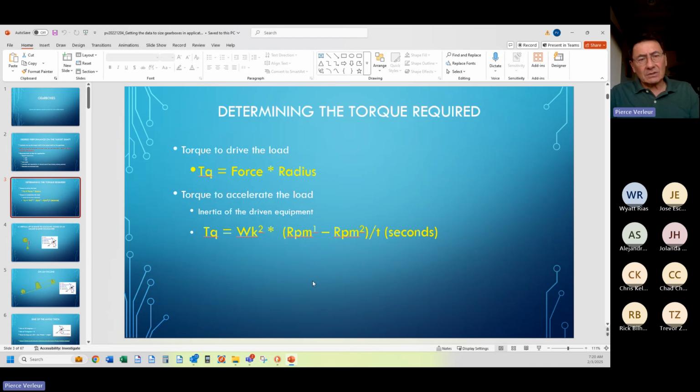You're going to have a monster engine. And that engine is way oversized if you just want to run the car at steady speed. Now, obviously, most of our cars are not like that. But the fact is that the acceleration time is what often becomes the limiting factor in sizing the drivetrain of which the gearbox is a part. And therefore, the running torque is pretty much covered because of the fact that you have to get to speed very quickly.